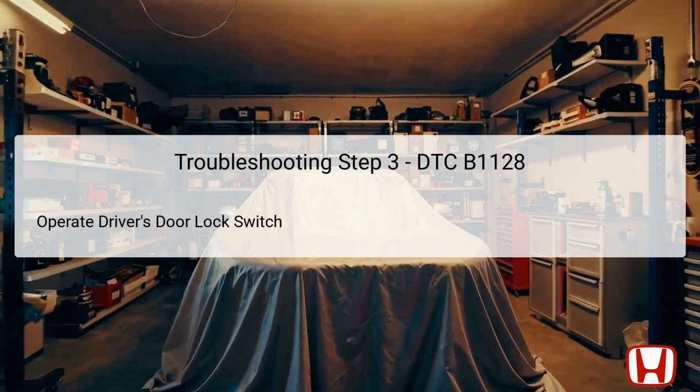Now, operate the driver's door lock switch to lock and unlock several times. This test is crucial for verifying the functionality of the door lock switch itself. If the switch operates correctly, it should provide distinct locking and unlocking signals without any glitches.